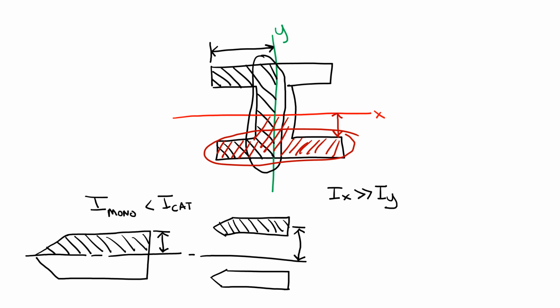There are a few things to note about the moment of inertia of simple water planes like this. Since the water plane areas are simple geometric shapes, the moment of inertia at the centroid can be found easily from derived equations. Second, whether the moment of inertia is taken at the center of flotation, which we'll say is right here, or at the reference point, which we'll say is right here, the moment of inertia about this axis is going to be the same, because the reference point and the center of flotation lie on the same axis.